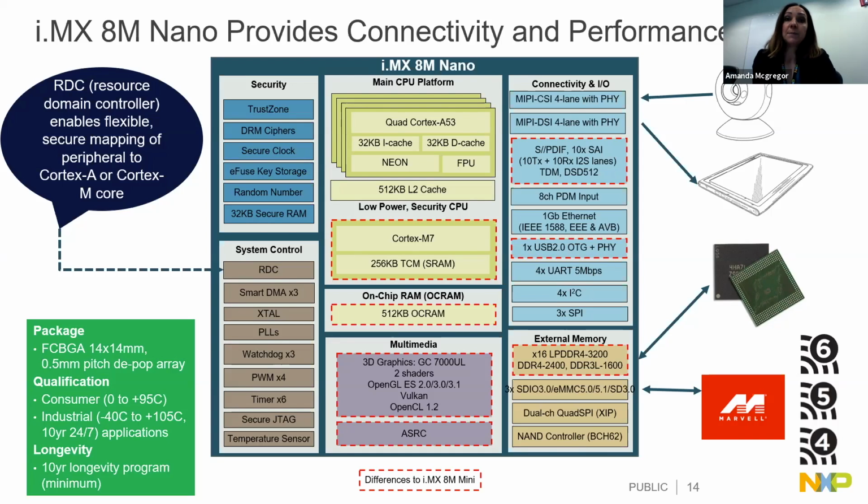It's new on the 8M Nano. What it does is it provides the ability to do sample rate conversion in hardware without loading the ARM Cortex-A53 down, which could actually take 1 to 2 cores without having a hardware ASRC implemented. So really, providing great efficiencies for audio and extending the capabilities in that space.